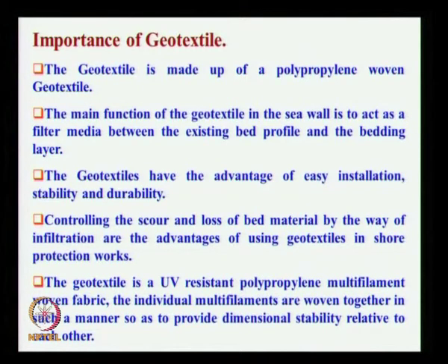What is the importance of geotextile? This geotextile is made up of polypropylene woven geotextile. Main function is to act as a filter media. Filter media means like our coffee filter only, between the existing bed profile and the bedding layer. Bedding layer is nothing but the filter layer. It allows the water to percolate, but it does not allow the seabed material to get into the bedding material. Bedding material is a filter material, either a sand or a stone of size up to 150 mm. So these two things should not come in contact.